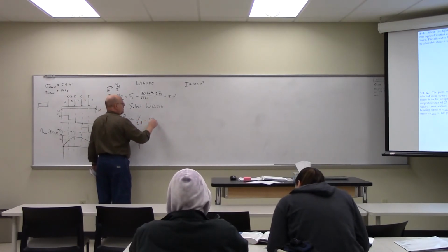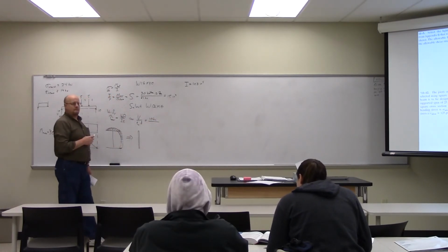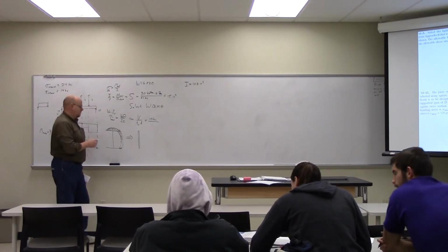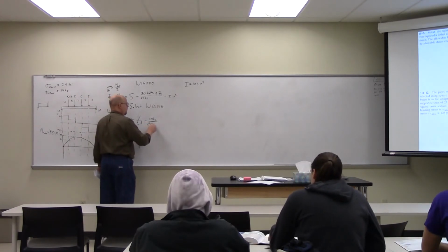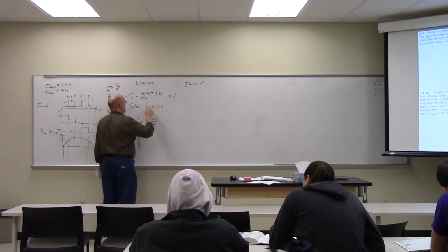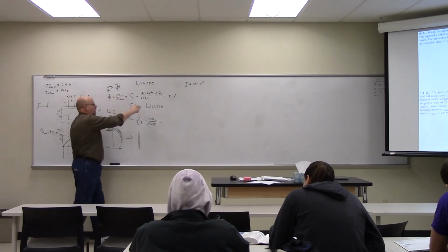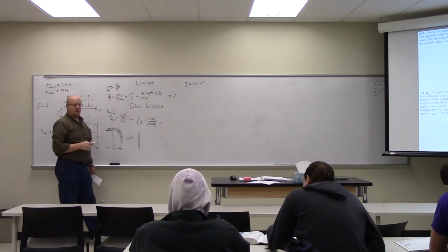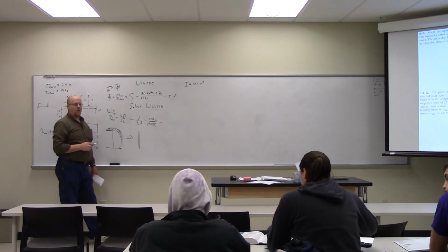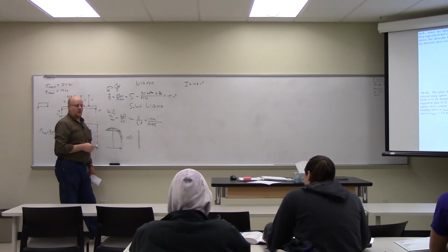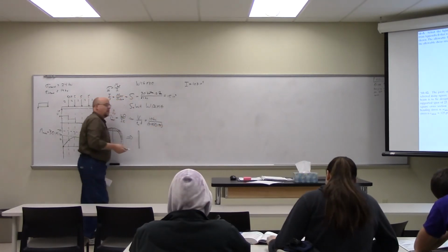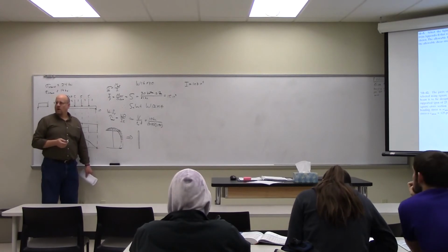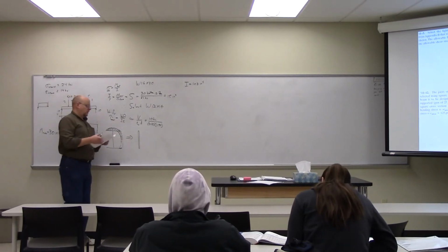So it's going to be 10 KSI over, what's the thickness of the web? The width of the web here? 0.22 inches. And what is the height of the web? Even though it's nominally, where are we? 12. What is the actual D? So from the very top to the very bottom? Yeah, the D value that's calculated for that. 11.99. Okay, 11.99. So it's nominally 12, but it's not exactly 12.